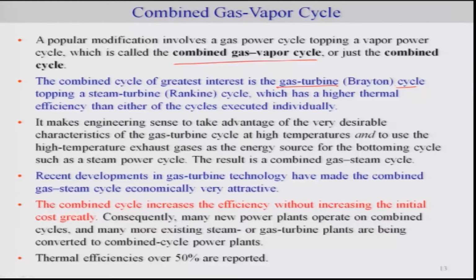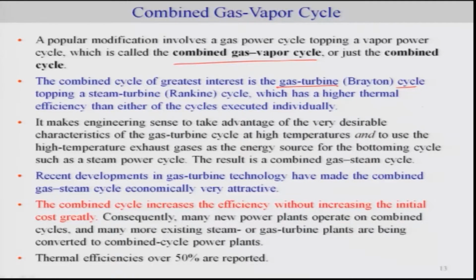That means instead of having a specific boiler or heat exchanger, you make use of the exhaust gas as kind of the heat exchanger. And this particular way of combining, the combined cycle, apparently has more efficiency compared to these two individual cycles. The recent gas turbine technology combined with the steam apparently has efficiency of more than 60%. So, these have become very popular and highly efficient.